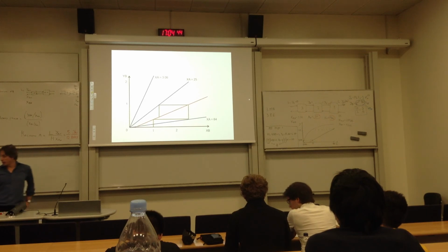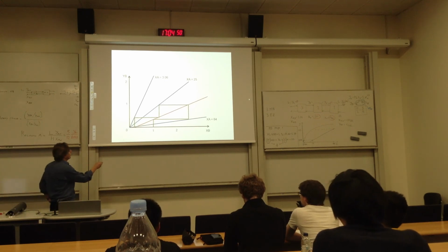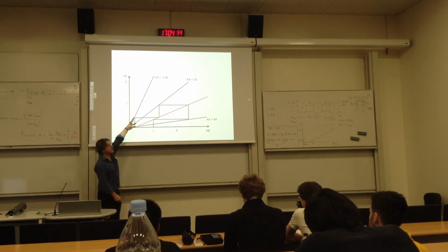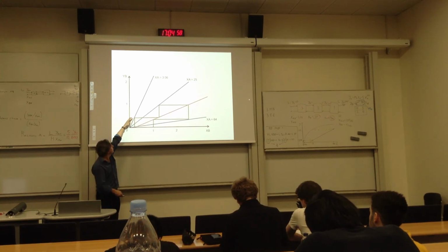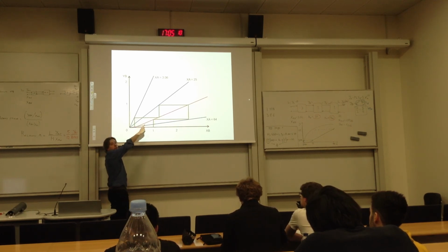And then you can find the conditions in the third equilibrium by going horizontally to the line corresponding to the last stage, the third stage. And then when you come here vertically, well, you find that you meet the red line at 0. So this proves that this was the right operating line.